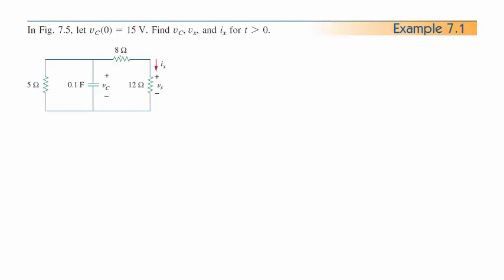So we have to find the equivalent resistance and put it in as a series circuit with this capacitor. That's really saying: what is the Thevenin equivalent? I'm trying to get a circuit that looks like this. This is a good use of Thevenin. I'm trying to get some Thevenin resistance to go with my capacitor. So how do we do that?